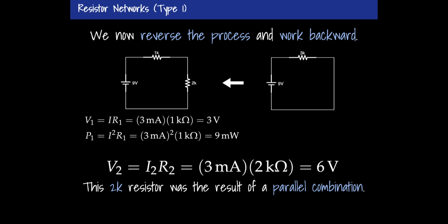That's what I've just learned there. Might as well calculate the power while I'm here. The power of the 1K resistor, I'll use I squared R because I know those numbers, is 3 milliamps squared times 1 kilo ohm, which is 9 milliwatts of power. When I say 9 milliwatts of power, how is that energy being used up? Well, if this is just a resistance, probably it's all becoming thermal energy. It's getting hot.